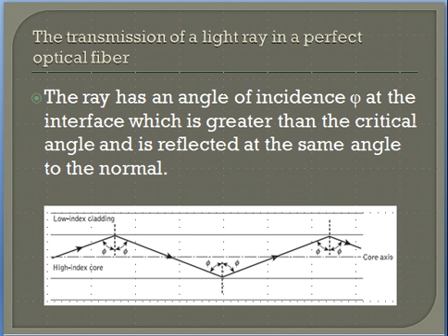This type of ray is simplest to describe, and it is generally used when illustrating the fundamental transmission properties of optical fibers. It must also be noted that the light transmission shown in the figure assumes a perfect fiber, and that any imperfections at the core cladding interface would probably result in refractions rather than total internal reflection, with the subsequent loss of a light ray into the cladding.